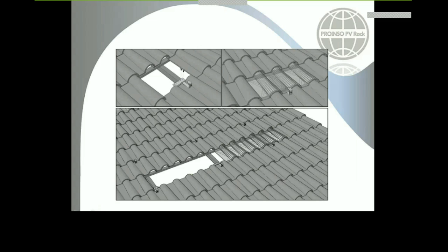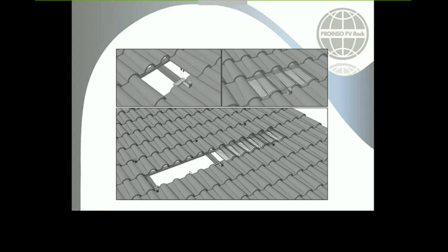As I previously said, if your distance, for example, is 1.5 meters and 1.2 meters is required, you could see this information is shown in our assembly manuals, okay? However, if you have not enough distance, you put a piece of wood in here, you fix it properly, and you could put a fixation in the middle, okay? Obviously, we always recommend you ask us any question, and we could revise all the installation before you do something that maybe could get some issues.